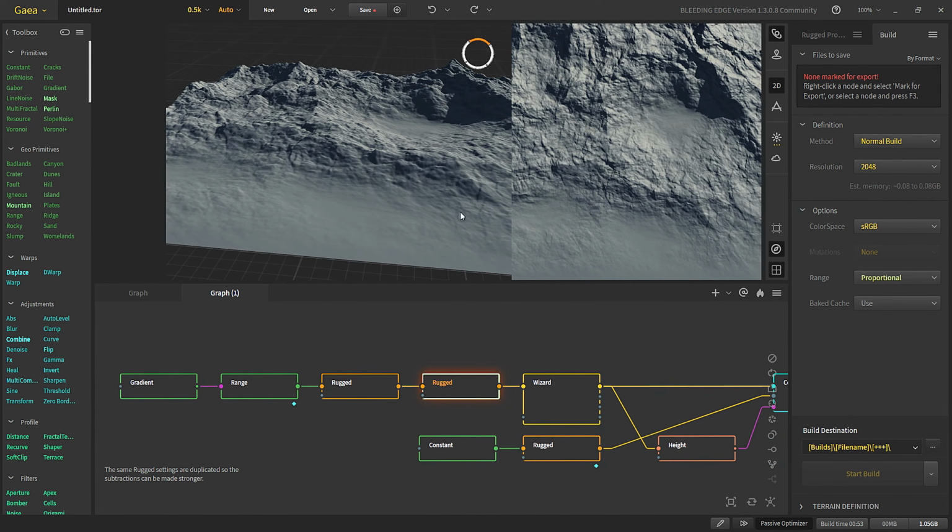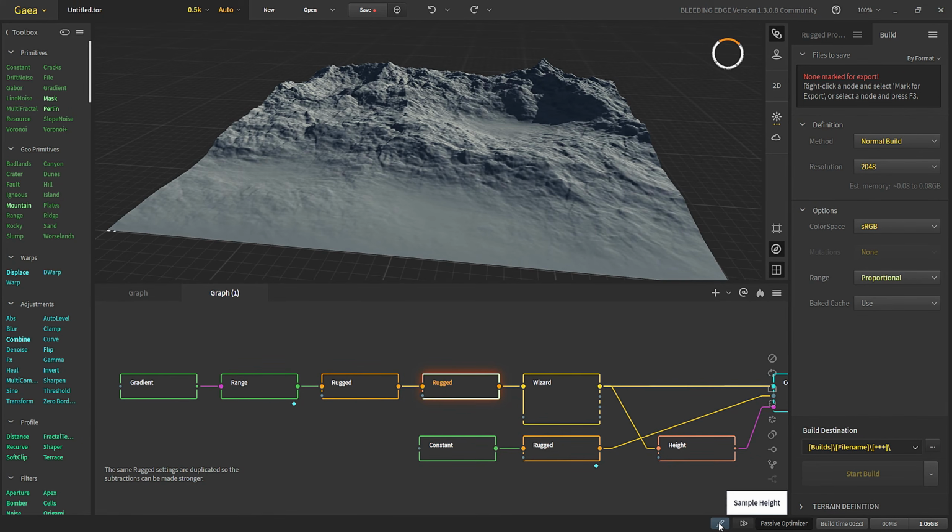And what the next one is doing, I'll show it from here. So this is the sample height. If you click on it, it will show what height this pointer is at. It will show the height here. So let's say this is 5 meters from our ground. This is 0. This is 3 meters. So we can see which pixel is at what height in our viewport. If you click on it again, then it will go away.